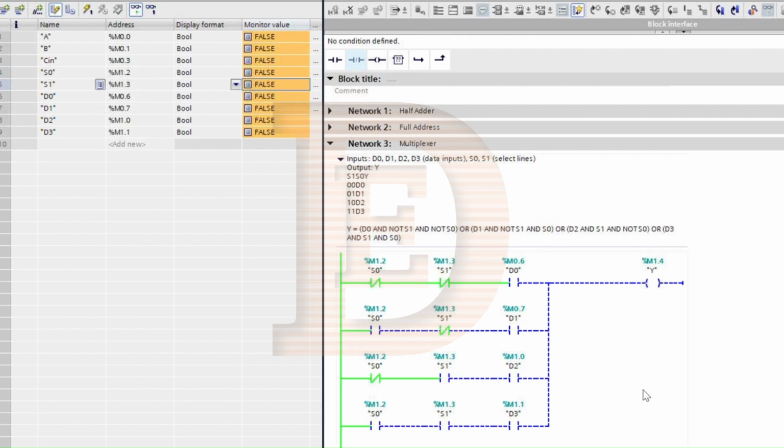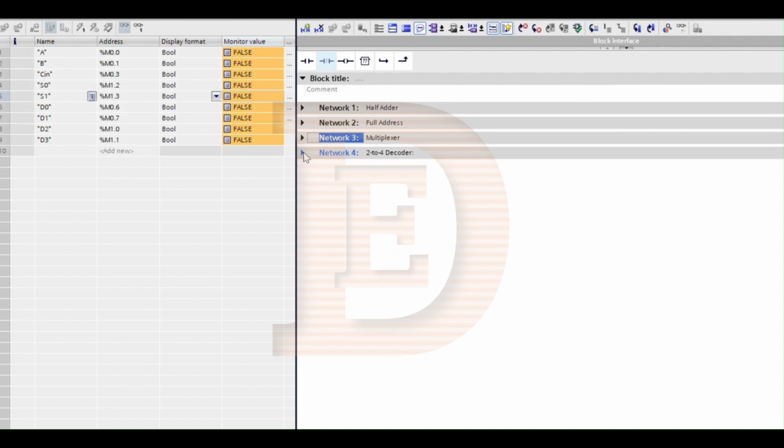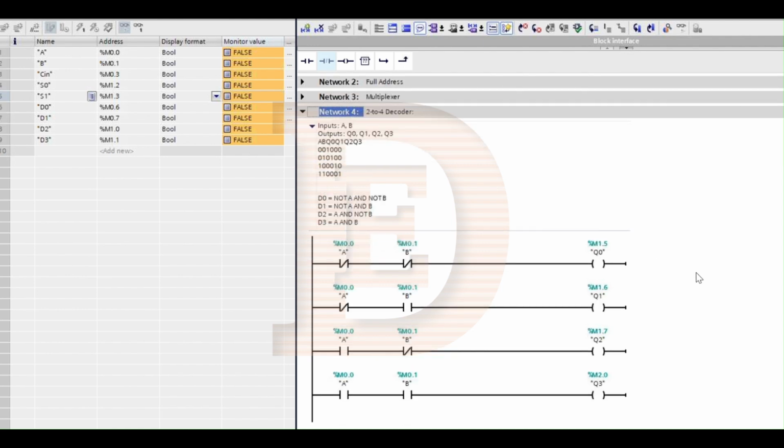And it's a bunch of switches that are selecting which signal goes to the output. Then we look at a decoder. A decoder is basically having output signals numbered in decimal, and then whatever that number, we build a set of input signals that represent the binary number. So if we have 4 outputs, I need 2 input signals to build the binary numbers from 0 to 3. That gives me the 4 outputs.